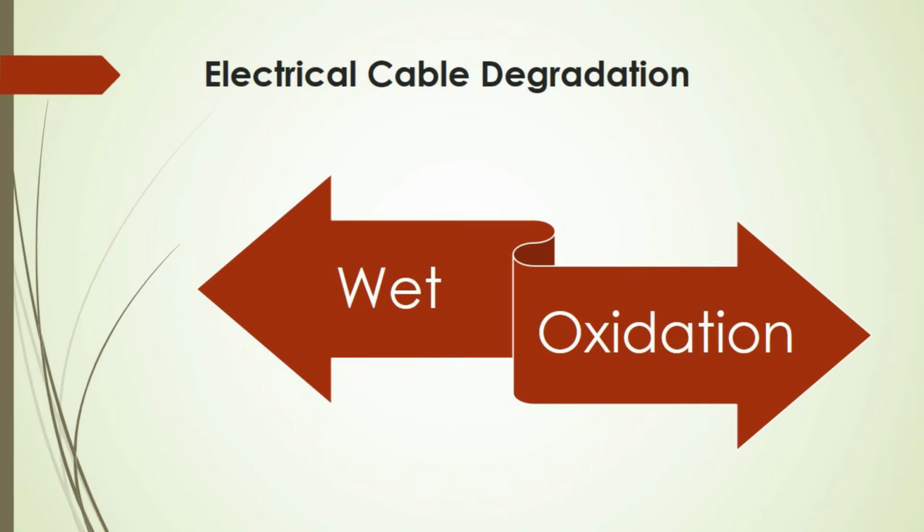Power transmission, as well as instrumentation and control cables, require durable and dependable polymeric dielectrics. Because of environmental conditions that might damage cable insulation, cables used in underground residential distribution, or what we call URD, confront substantial issues over time. Moisture and electrical stress can cause the dielectric characteristics of the polymeric insulation to gradually deteriorate and eventually would lead to full deterioration and finally failure.